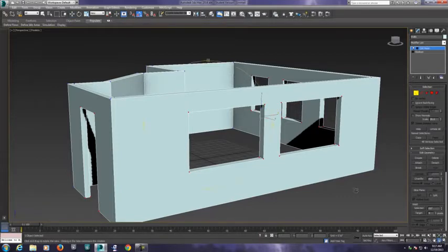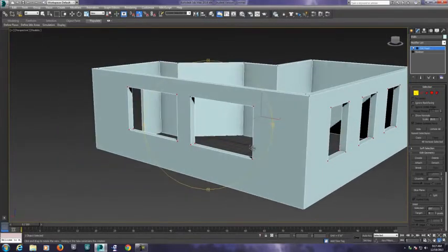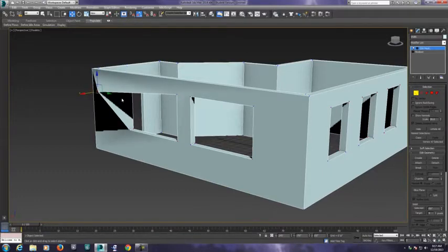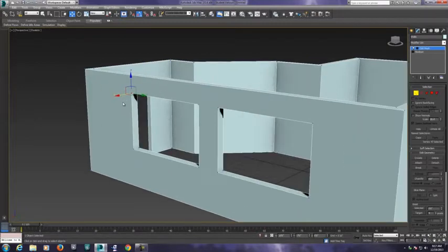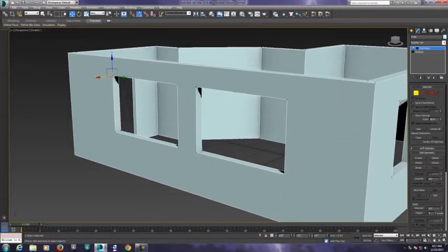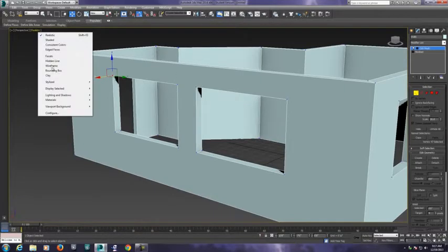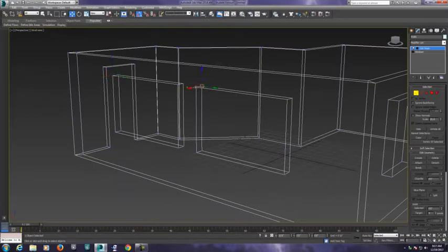Now just remember, when you resize something, that we have a thickness here. So if you just click one vertex and you move that vertex, you're actually screwing up the walls. If you want to move an entire window, you have to get the vertex here, and the one that's hidden back here. And if I go into wireframe, you'll see that there are these. That's a common mistake that people have, is in one view they just click and they pull, and then they don't realize why the whole segment doesn't go. Worst case scenario here, oops, don't want to do that.